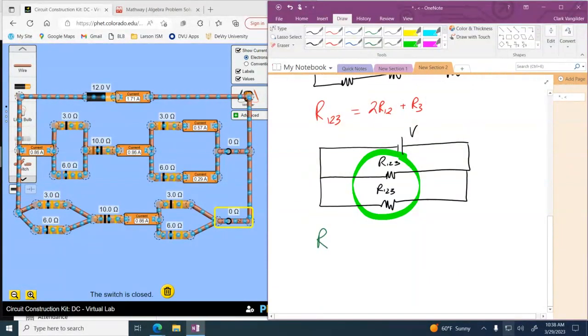When you get to the last step, you would just call that R usually. It's your total resistance. You could say R subtotal if you wanted. I'm just going to use no subscript, meaning the final total amount. And again, since it's 2 identical resistors in parallel, you know that it's the product over the sum, which would be more simply written as R123 squared over 2 R123.